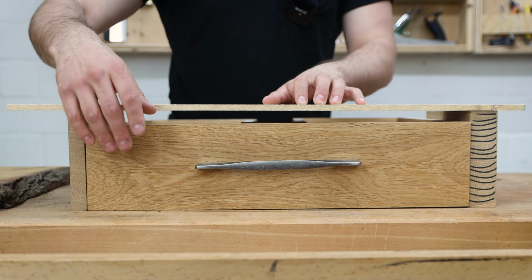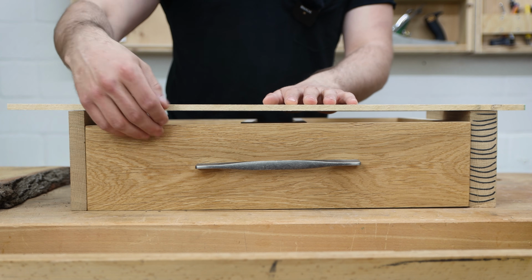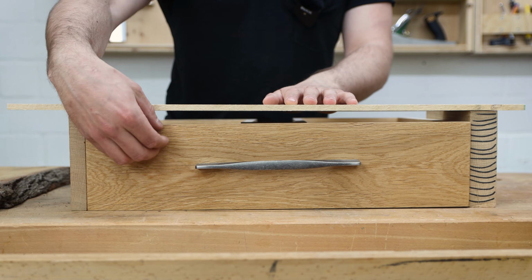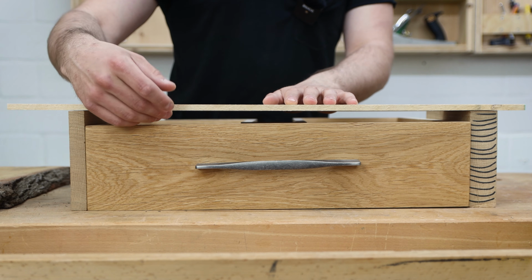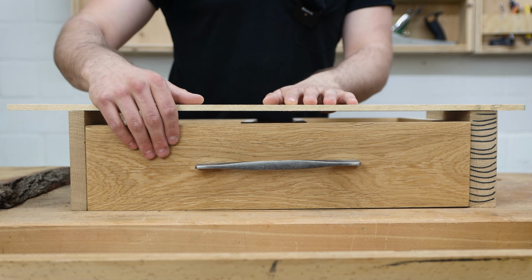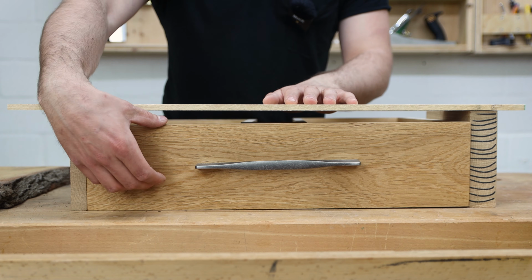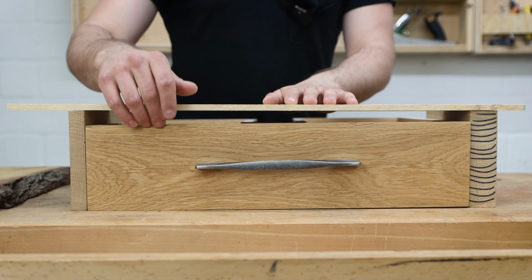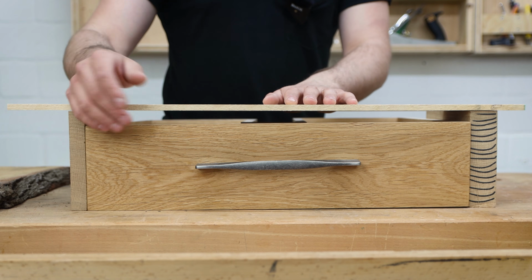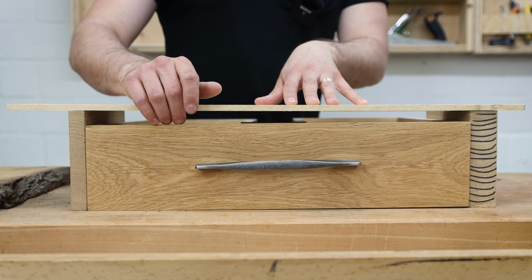If you build your drawer in the summer where it's drier, you know in the winter it's going to be wetter, it's going to expand, so you have to leave a bigger gap for the seasonal wood movement. If you build your drawer in the winter where it's more moist, you know it's going to shrink in the summer, so you can get away with a smaller gap actually. Again, if you know you're going to ship your furniture somewhere or it's going to live outside and change your moisture content, now you know how to account for that.